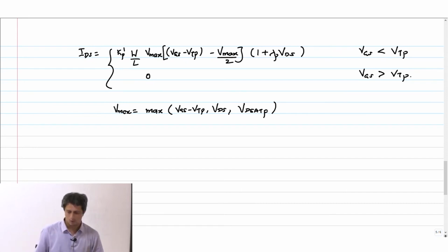So what we will do now is to simply compare what the sign of each of these parameters should be. We had 5 parameters that defined the level 1 spice model for the NMOS transistor. We have similar 5 parameters here. So I'll just write that on one side: K prime, VD sat, lambda, VT naught and gamma.